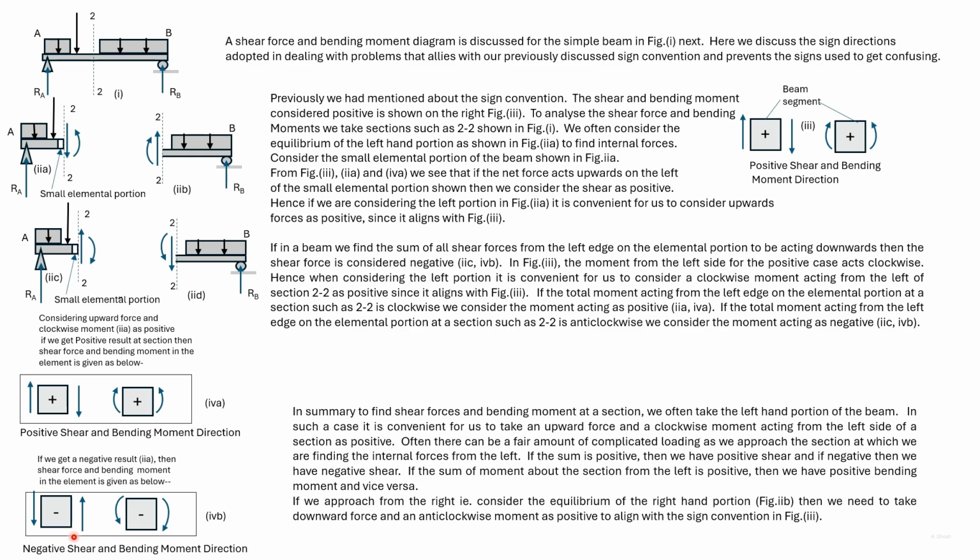For equilibrium, on the right side we'll get a force acting upwards. So the negative shear force value that we have got matches with our sign convention. So we have established that considering forces upward to be positive from the left side matches with our sign convention for shear force.